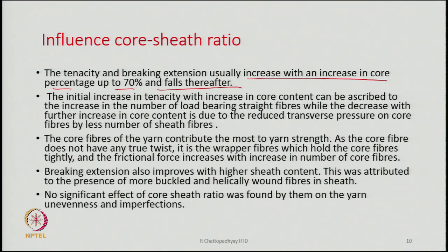It is the core fibers, which are practically straight, that are going to support the load, because they are more or less straight. But it is the sheath fibers which are wrapping the core, and these fibers are trying to develop or generate transverse pressure on the core, and by that they are increasing the frictional resistance to slippage of the core fibers.